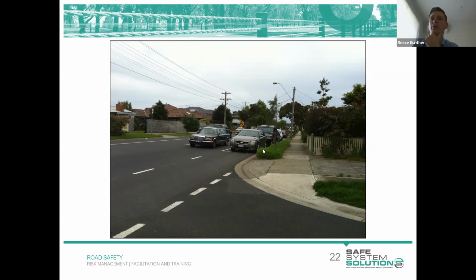So what we can do is banned parking, timed parking. We put a curb build out, which provides for sheltering of vehicles for the turn maneuver, which is good, but allows us to move this hold line closer to the traffic lane, which gives us extra sight distance to an approaching or an oncoming vehicle.